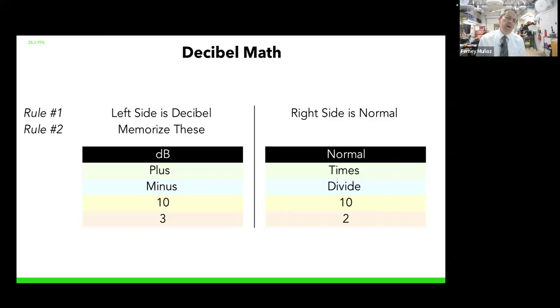We hear all the time, "Oh yeah, we design our Wi-Fi to be negative 65 dBm." Actually, before we used to design for negative 72 dBm. What does that mean? And why is negative 67 better? But then others say, "Oh no, negative 65 is too weak." And I had a hotel chain where they said, we need to design our Wi-Fi to be negative 60 everywhere. Negative 60, that's really, really strong.